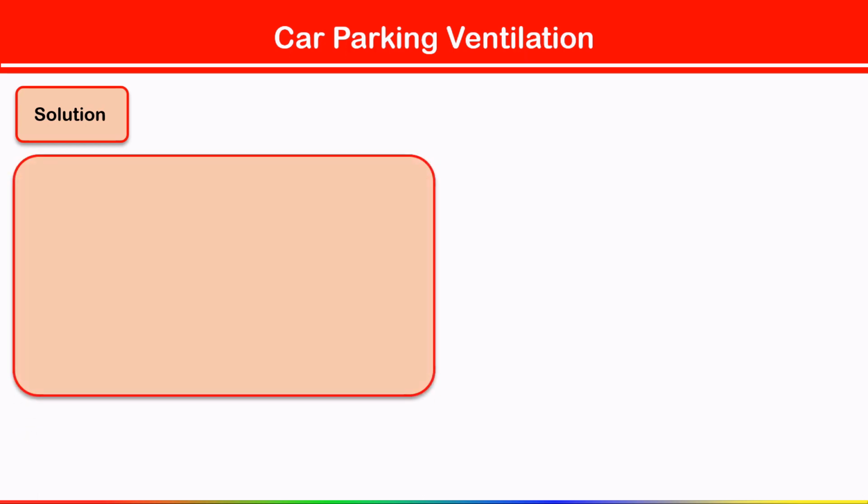Now once you get the area of each mesh, suppose my mesh and my filter are the same. For a square mesh, if the side I have taken for the mesh is small a, then the area of the mesh is a squared, equal to 1.52. So finally you will get the side of that square mesh as 400 mm. So this is the size of your filter or mesh, 400 mm width and 400 mm height, because all sides are equal. Now we get the mesh size.